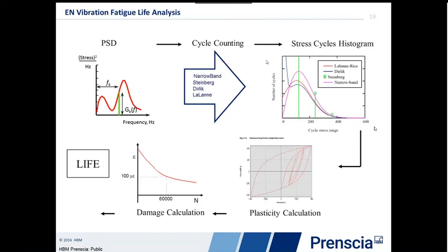What we're doing here is we'll go through the stress cycles and identify the cycle that is the largest load, and that generates an outer loop. Again, once I do plasticity, I'm going to see hysteresis loops, stress-strain behavior come out of just the elastic results. Once I have the outer loop, we have rules built in that look at each other cycle. And each cycle now we know has to be in that loop, but we're not quite sure where.